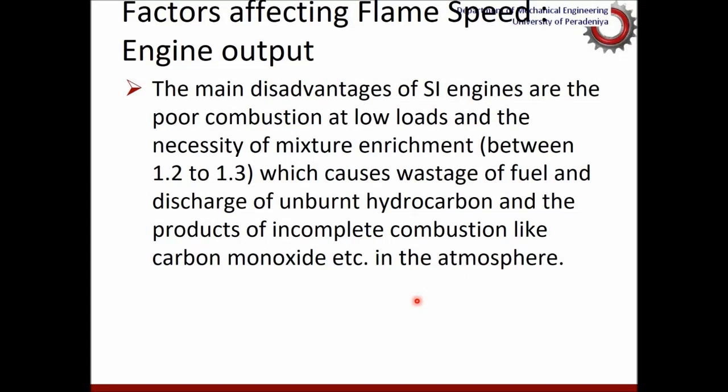So usually under low load conditions, we tend to make the mixture a little richer, so that the combustion would be enhanced. But again, when you burn rich mixtures, there can be drawbacks or negative effects. Particularly, you will release more unwanted exhaust gases, mostly hydrocarbons, from the tailpipe. So that will not be good for the environment.